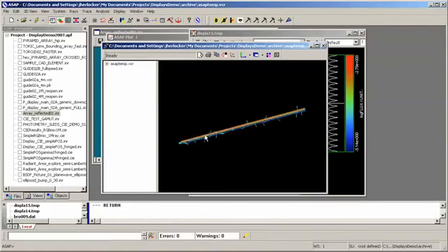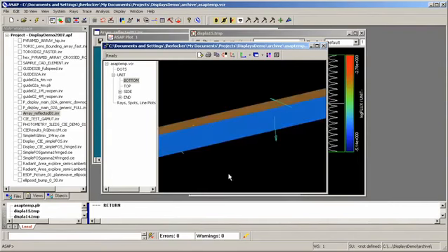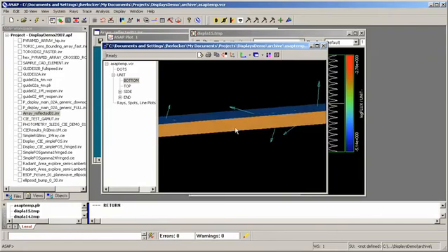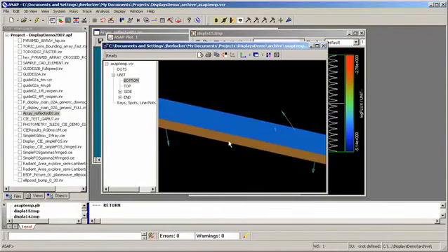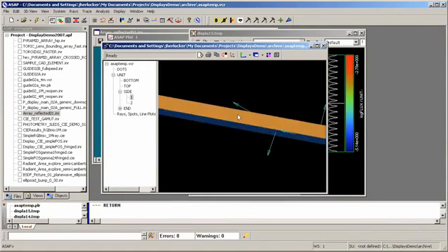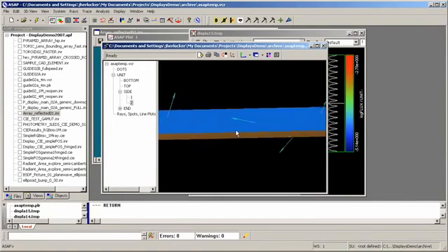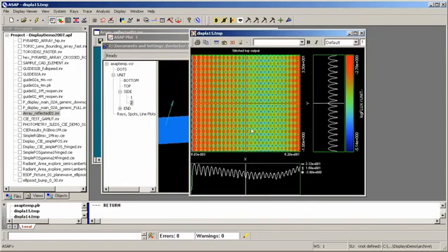So if we look at this in the 3D viewer, you see it's a long, skinny display. And what we have here is these two narrower sides are made mirrors, so that it simulates the effect of having many of these stacked side by side. So we would have this one, and then next to it over here there would be another, and next to it over here there would be another, and so on. And we can stack up the irradiance results to see what this might produce if we build a whole display that way.